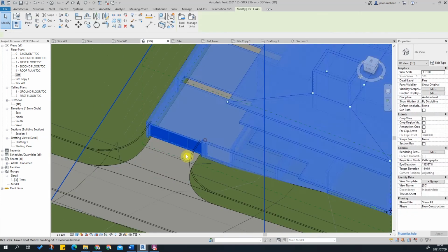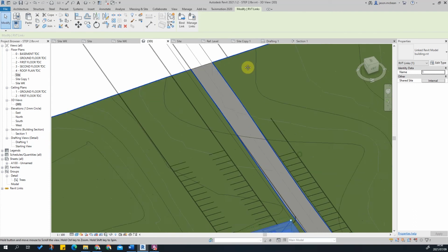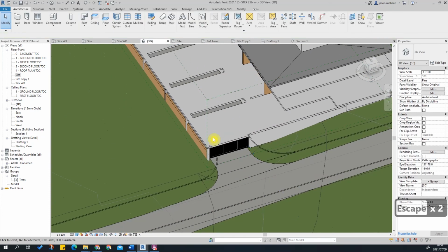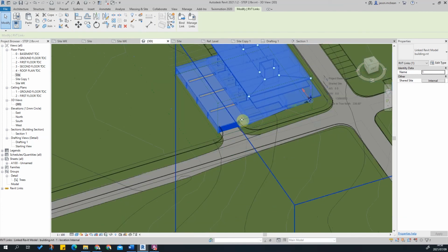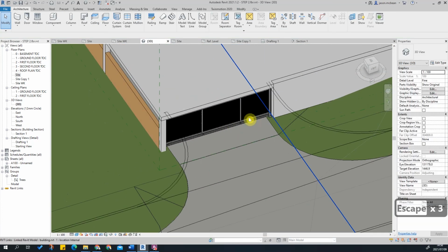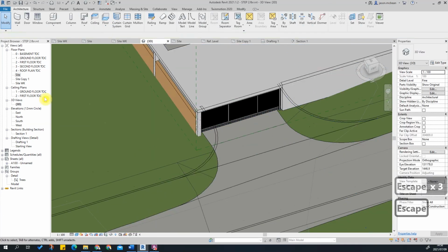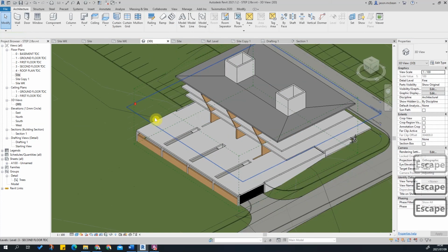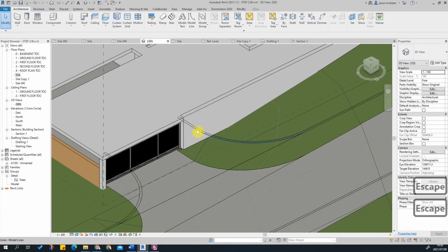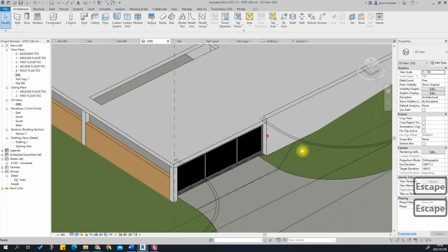In this instance, we need to switch this off because generally we don't show this roof level above. I'll show the outline of this level above, and I need to just indicate where this gate will go. So if you don't have a 3D gate object, you can simply draft that in on the site plan as well, either using model lines or detail lines. I would recommend doing that purely as 2D line work, like I'll do the services now.